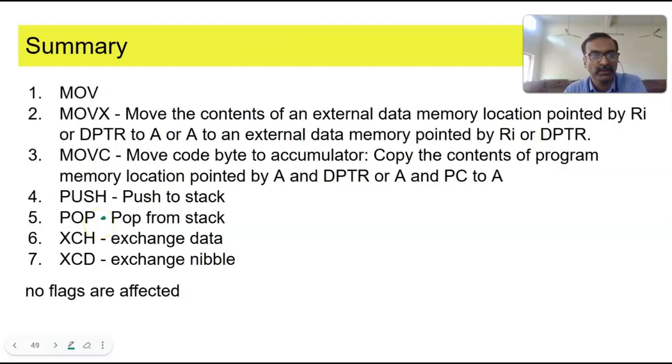So let us come to the summary of various data transfer instructions. We have seen every one. We have seen MOV, with different options. Then MOVX, to move from the data memory. MOVC is used for moving from the code memory or the ROM. Then we also studied the PUSH and POP instructions, and XCH and XCHD, exchange nibble.